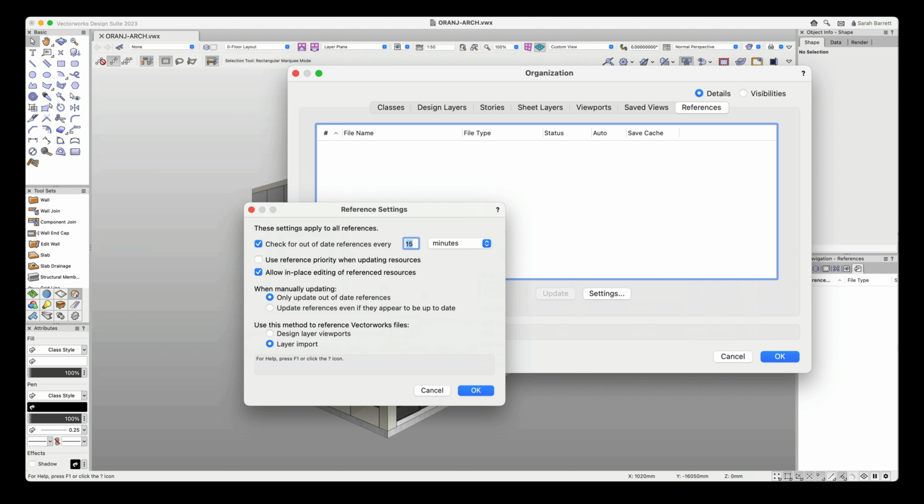Because this form of referencing creates classes as well, it's important for your MEP engineer to organize their files well. This is not really an issue with referencing an IFC file because the classes that are created are IFC object types, so it's already standardized. At the project's completion, you'll have similar deliverables as to a project drafted in 2D, a printed drawing set. The difference will be how you got that result, and in all likelihood, many fewer change orders and RFIs to deal with.